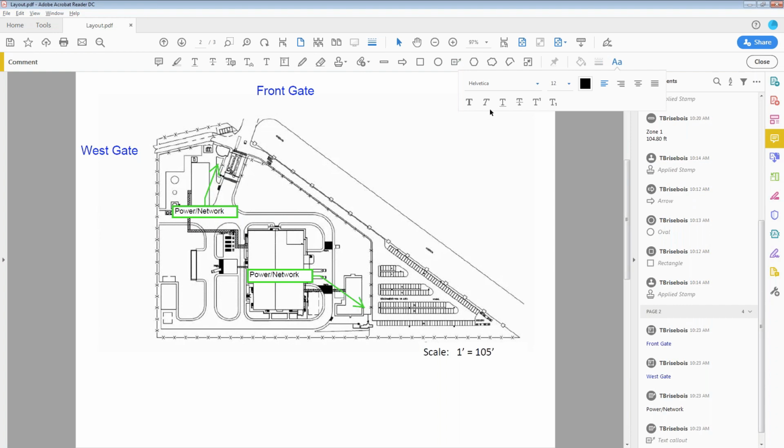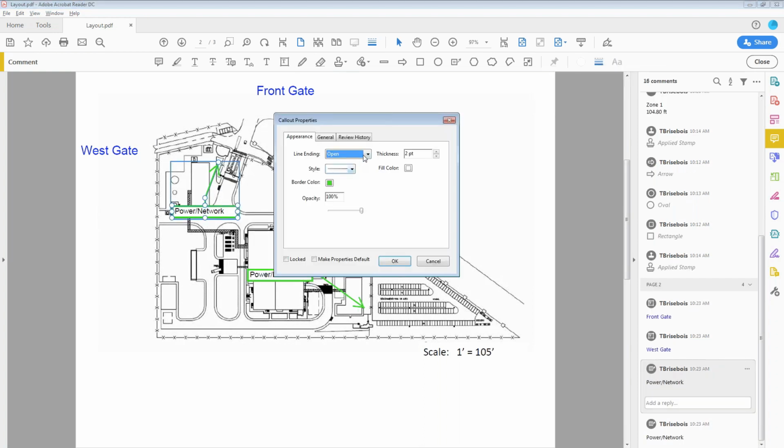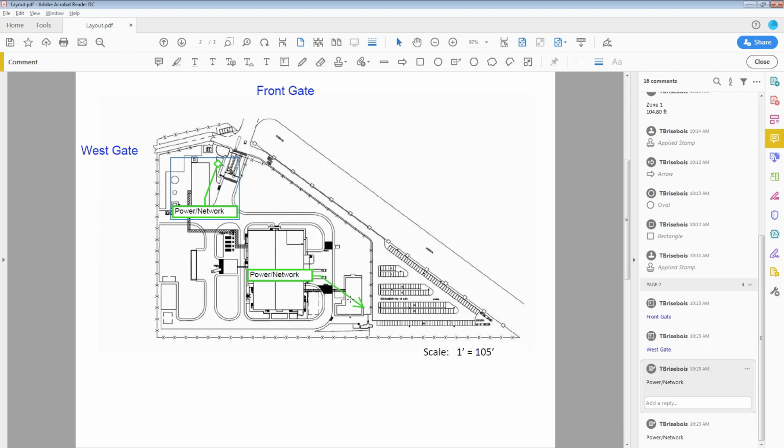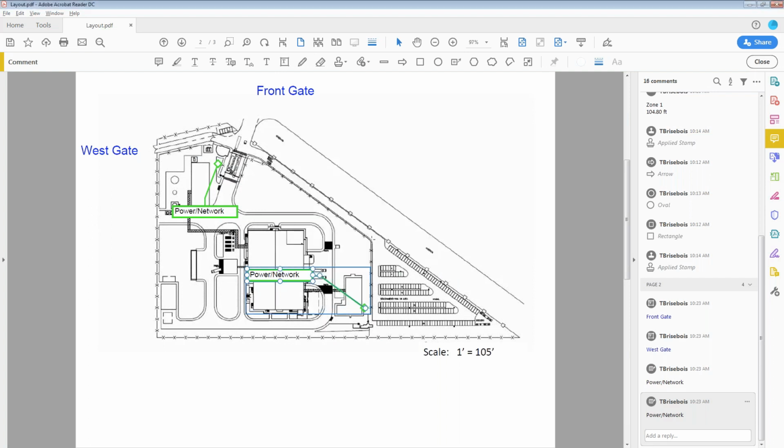So I'm just filling up the data that I have with any information that was provided to me. Now I can also change properties, in that I might want to have something like a diamond call-out instead of the arrow. We maybe want to leave arrows to dimensioning and maybe diamonds to certain positioning. So we've got that in there.